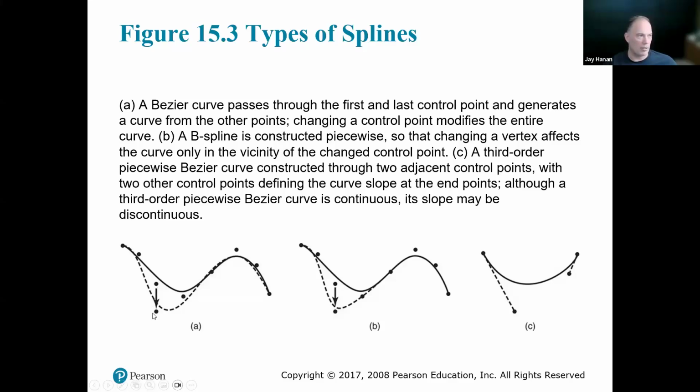In the case of this curve, one of the points that they make in the book is you make some small change here, and there's a more global effect on the rest of the curve. You see implications of the dashed line here changing far from where you made the dimensional change. Whereas if you use more of a spline technique, you still see some deviation far from this change, but it's minor compared to no change.